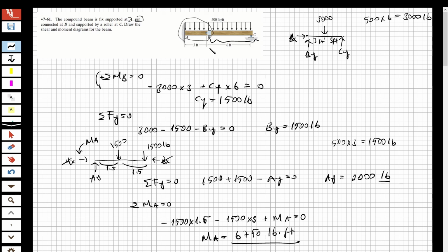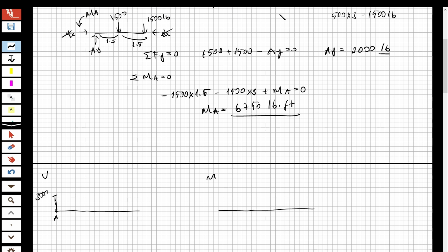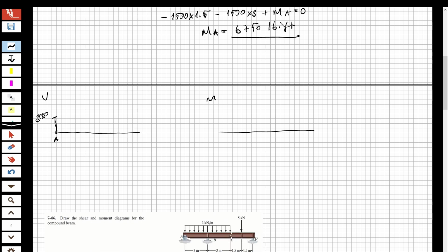Look at here, I'm going to decrease as triangular. This is pin, so I can decrease totally with the whole shape, with the whole beam. Okay, so it's going to be something like that. 500 multiplied by 9, the whole length of the beam, so 4,500, right? So I'm going to decrease by 4,500, and I'm going to reach the point 1,500.